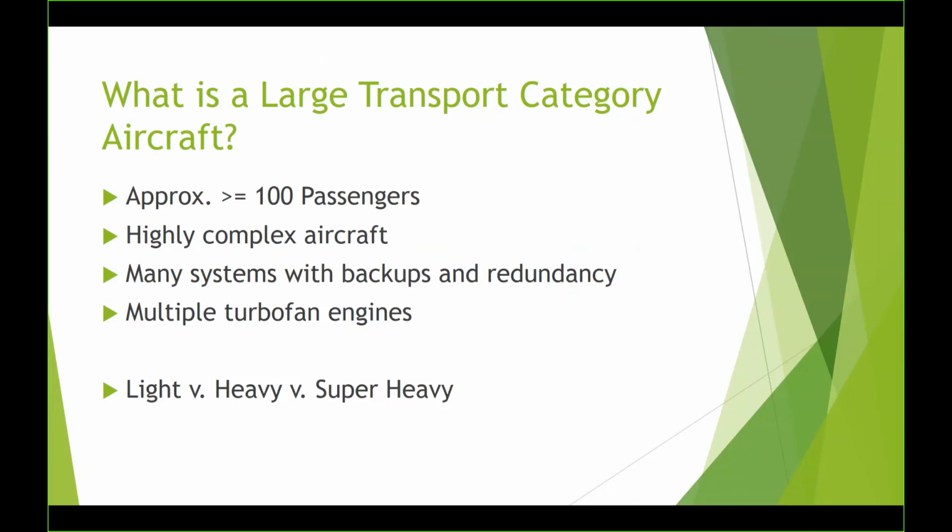Anyone know that? The one single aisle airplane that gets classified as a heavy is the 757. For some reason, the design of the 757 produces larger wake vortices, bigger turbulence than a normal single aisle airplane does. The newer ones with winglets on them help somewhat, but they still have to space planes out. Super heavy is getting into your 747s, A380s, the double-decker type stuff.